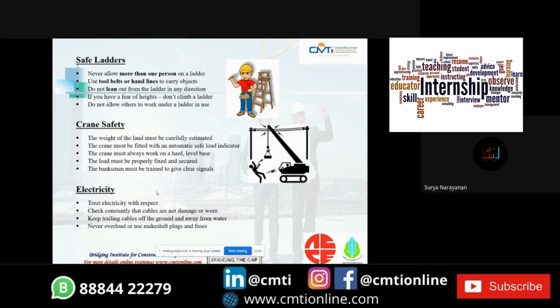So these are the crane safety rules while working on a site. The weight of the load must be carefully estimated so that the ground can withstand the crane weight. The crane must be fitted with an automated safe load indicator. The crane must always work on an even level base. The load must be properly fixed and secured. The banksman must be trained to give clear signals.